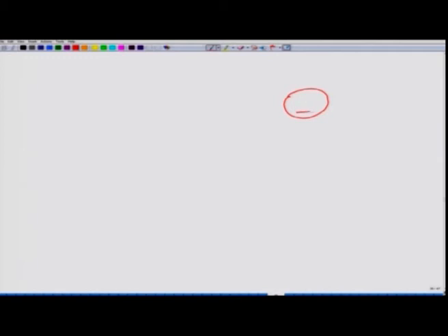So, let me now draw the base like this, and you have emitter. Input generally we keep on left. So, this is the input, this is the emitter side, and this is the collector side, and let me do it for NPN. So, the arrow should go from P to N, and hence the arrow should go this way, NPN. So, this base is now P, and this emitter is N, collector is also N. So, emitter will have this arrow going from P side to N side, and then our circuit.